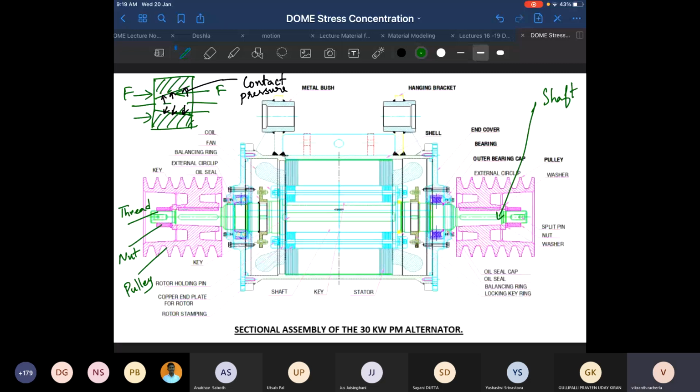Now, what is this thing over here? This straight cut with these circular ends. What is this portion? A key slot. Okay, so this is a slot for a key. So you use this key along with the tapered surface to transfer the torque.